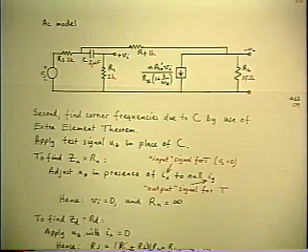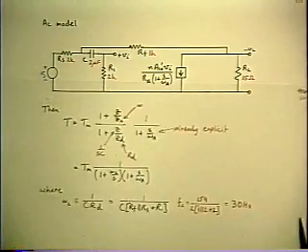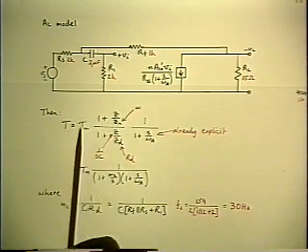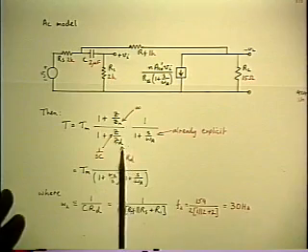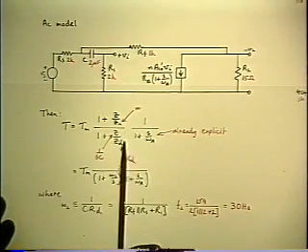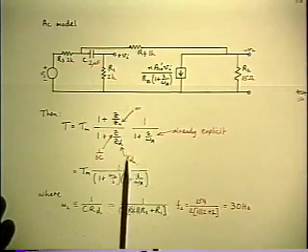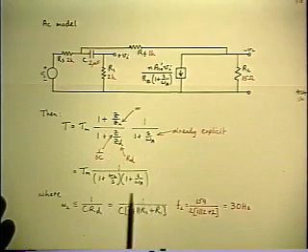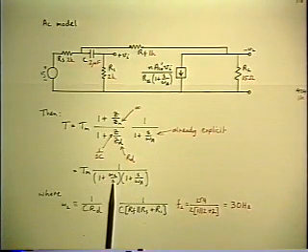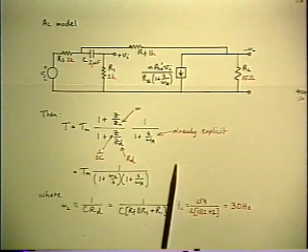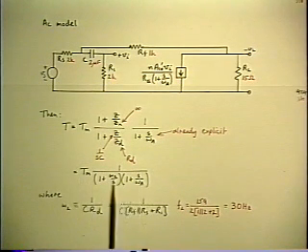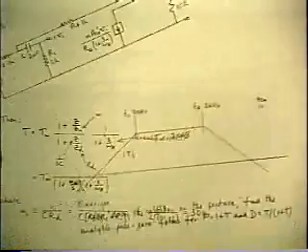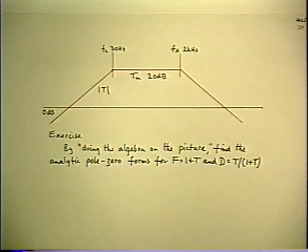So it goes away. So the bottom line is you restore the frequency response for the loop gain by multiplying the midband value by the theorem correction factor for the series element. So the Z is 1 over Sc, the Zd is Rd, which we've calculated, the Zn is infinite, it goes away, and that leads to an inverted pole at omega 2. So we end up with a loop gain that has two poles, one of them normal and one of them inverted, and that's what the loop gain looks like.